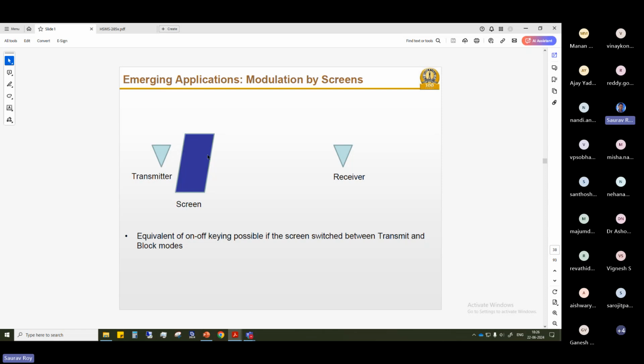So by changing the defined conditions in the screen, the signal passes through the screen and goes through the environment, or the media in between, and the channel will be different, because obviously it acts like a window, right? If you just close and open the window, that will determine how much signal goes from the transmitter to the receiver. Okay, now at the receiver, if you just record these signals for defined combinations of the screen, it will give you a constellation or a signal set that you can use for your codebook for your signal transmission.